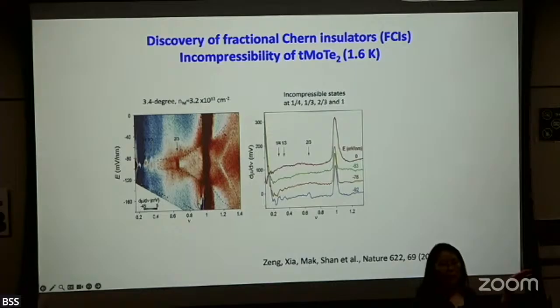So you have some kind of background, but over a very small doping range, you have a sharp step, and that step measurement is typically reliable. I have to mention that all different scanning probe compressibility measurements, even with the SET, always get this kind of background. So that probably needs more controlled experiments.